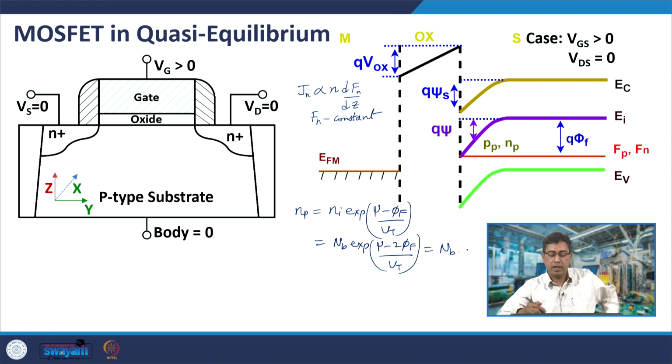You are increasing the gate voltage, so the silicon body, the neutral body, would have the same concentration. The entire bands would move upward, so to say, and since they are moving upwards, you can depict a larger band bending here.